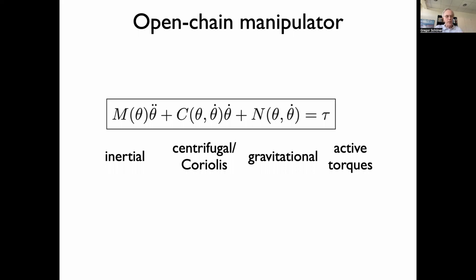The base frame is where the robot is attached to the ground, to the earth that absorbs all energy, or all momentum, ultimately, and then you attach a frame to the next element of the chain. And in the Denavit-Hartenberg framework, you do that with respect to elements of the chain where there is a degree of freedom, for instance, where you have a hinge joint.